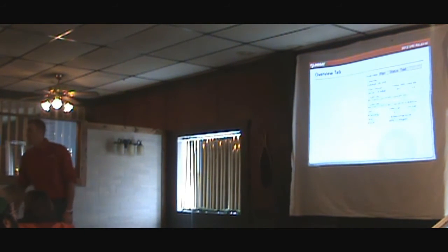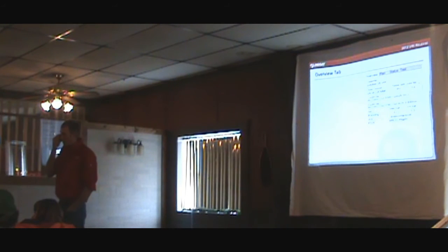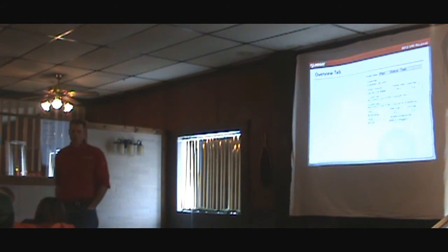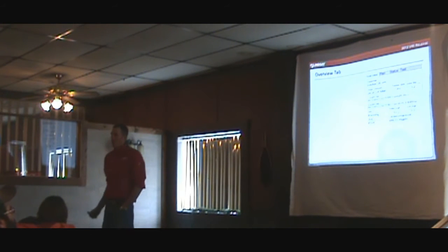One of the things that we found out with the one we put up: the aerial images that you get, the Google Maps or wherever they might be, after you lay those out, you should go out in the field and check. At least a spot check. Because they end up being dramatically different. That's a very good point. It's just an update thing.